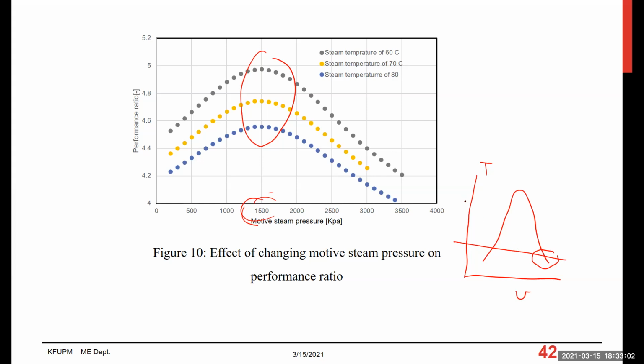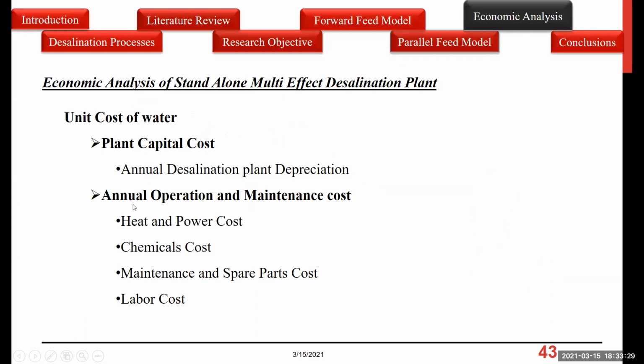But at higher temperature or higher pressure, as you are seeing here, it's 1,500. At this condition, the value of the specific volume is less, which means that you can use smaller pipes. So this is also going to help us in having higher pressure, which means higher temperature, so it will not condense on the way in the pipe, and the pipe will be smaller in diameter. So it's another benefit that we are getting from operating this unit.